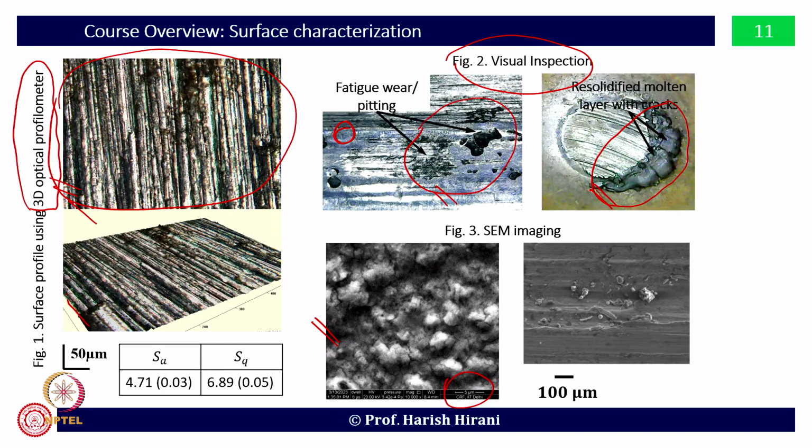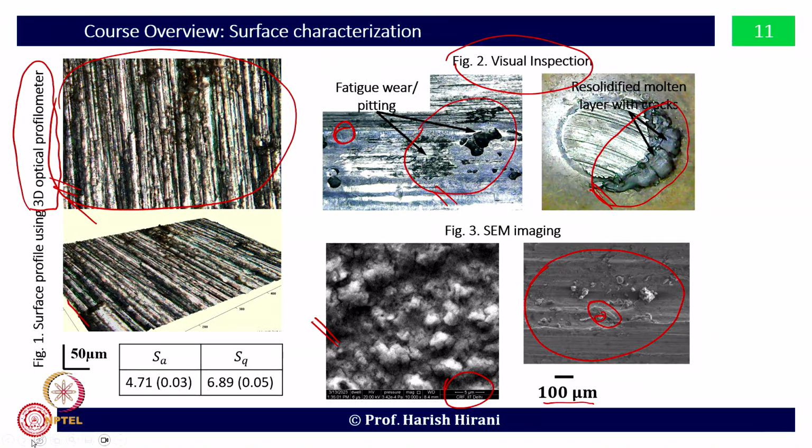So, this is very important, and we can show you here that there are various mechanisms. Even in the wear mechanism, if I find some sort of long particle, what we call a wear particle, it is cutting wear, but here we find some sort of spherical particle, which is fatigue wear. So, even the wear phenomena can play a major role, but there are multiple phenomena. It is not that I have studied only adhesive wear, so I will say okay, adhesive wear I can deal with. There are a number of phenomena. We need to figure out which phenomenon is the root cause and how it is leading to the next phenomenon. So, this is interaction, and we need to understand that. This will also be covered in this course.